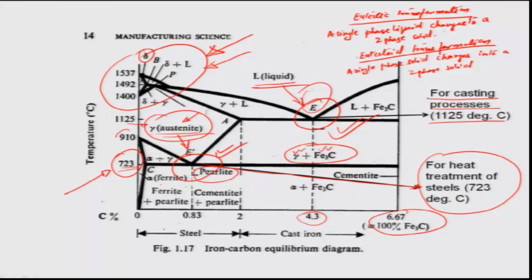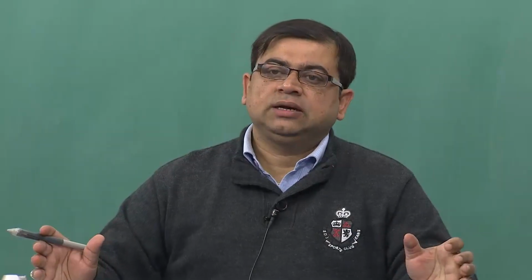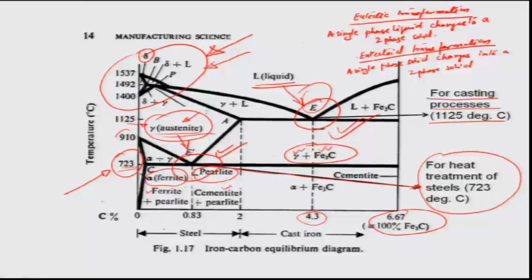So, it is a combination of cementite and ferrite, ferrite being the alpha iron, which we commonly know as the BCC crystal, and cementite is Fe3C. So, basically again it is another case where the solid that is formed has a continuous distribution of both the alpha as well as the cementite, the ferrite as well as the cementite, all through the crystal.